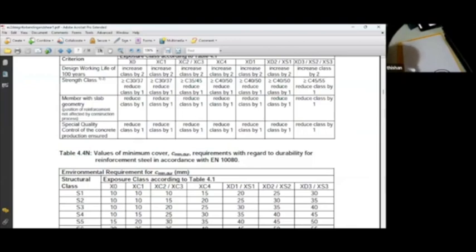But you can see in Eurocodes, it is 35 millimeters for all. Even in slabs, you need 35 millimeters unless you can assure that the slab is cast with special precautions that 25 millimeter cover can be assured. Sometimes it's very easy to take cover meter readings and assure that the 25 millimeter cover is there. So in slabs, if you want, you can use 25 millimeter cover, but you have to do a survey and show the 25 millimeter is there.